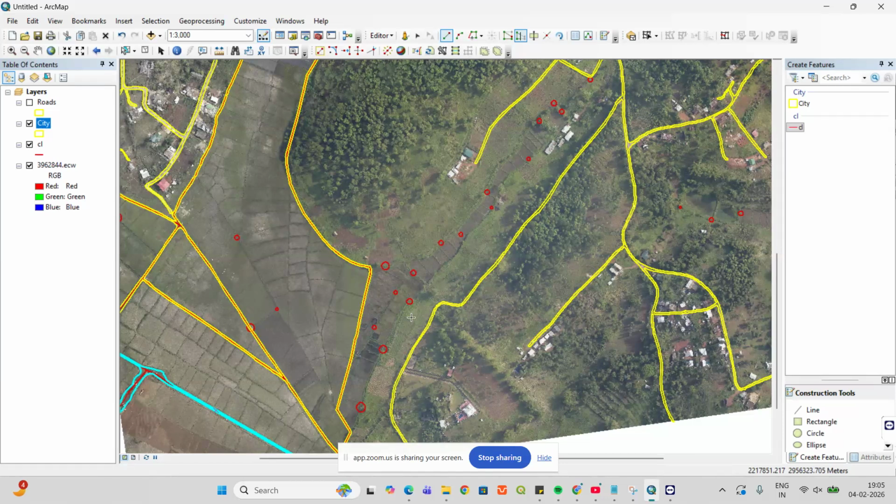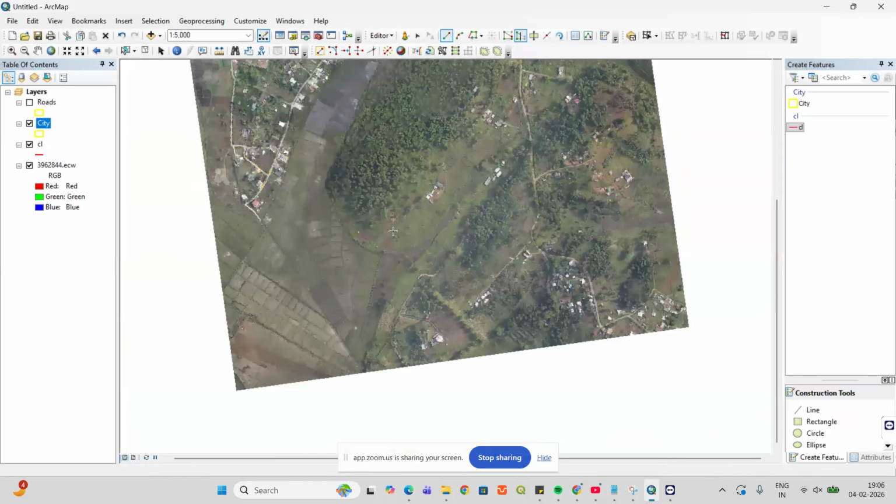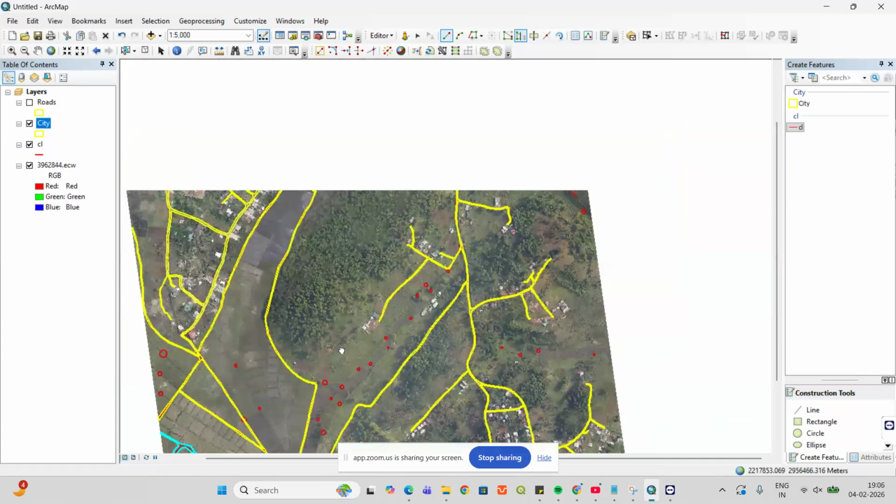So number of flights increases, number of images increases. If number of images increases, the production time, everything actually increases. And also, to get to this very accurate 2D, we also had more GCP. Normally we'll do 5 GCP per square kilometer. In this case, we had somewhere around 20 to 25 GCP per square kilometer in order to make it smooth and the terrain more clean without errors. So the tougher the terrain gets, the more complicated it gets also.